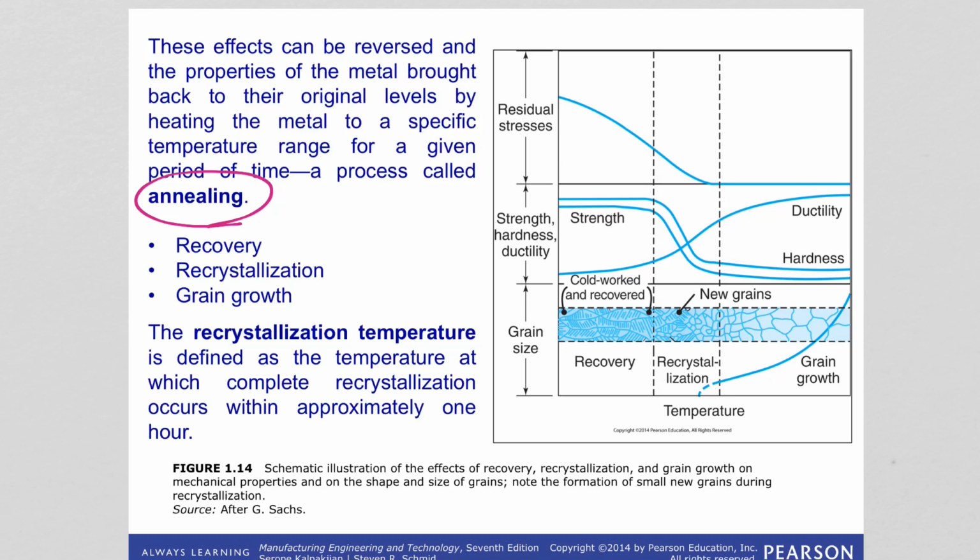So think about it this way. You are changing the shape of a material, right? You are doing cold work, and how much can you keep changing and deforming the material? Because every time you work on the material it gets stronger and stronger, and getting stronger means getting brittle, or a reduction in ductility, right?